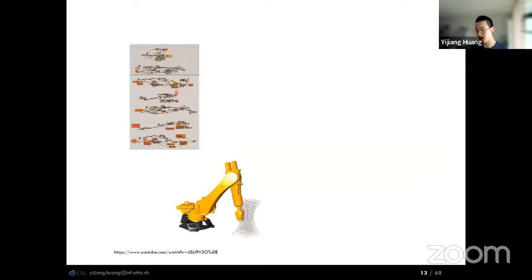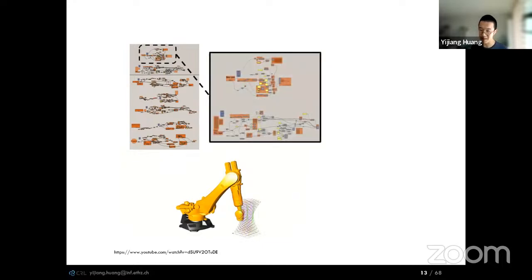So most current architectural robots use CAD software to do some kind of semi-automated programming. Designers use visual programming platforms like Grasshopper and Rhino 3D to program robots point by point based on digital models. But this process takes a lot of time, and the final generated programs are usually not really reliable. Using the analogy of a 3D printer that almost everyone is quite familiar with right now, this programming process is like writing scripts to generate the G-code for each single unique geometry that you're trying to print, by the designers themselves.